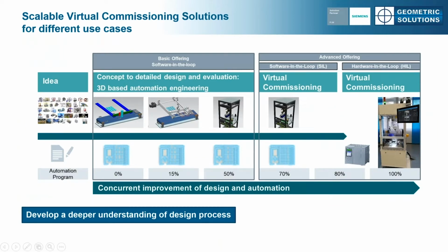Now, if you think about a typical workflow, we always start with the idea. And then after we have the idea, we start making some conceptual designs. And as the conceptual designs grow, well, then we get the real machine. Well, we can do the same thing when it comes to writing our PLC code, that as the design goes from concept and starts to mature, our PLC programming can be done the same way. We don't have to wait until the machine is actually built to do all of the commissioning.